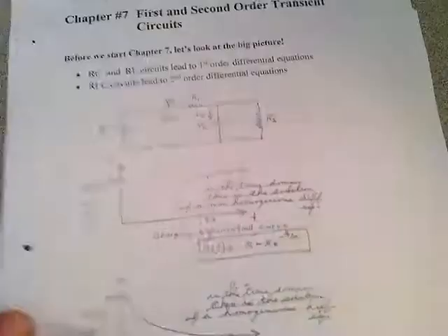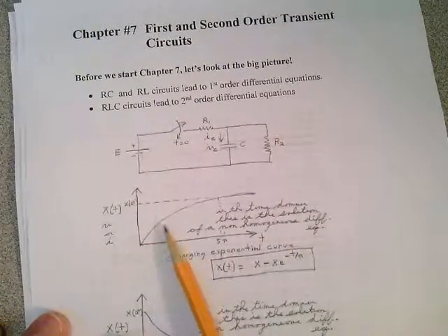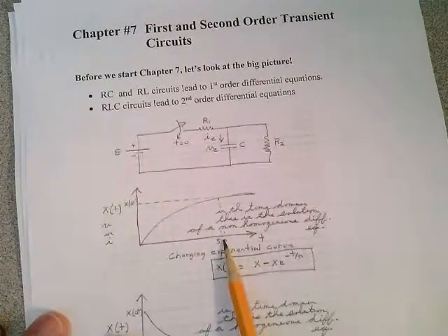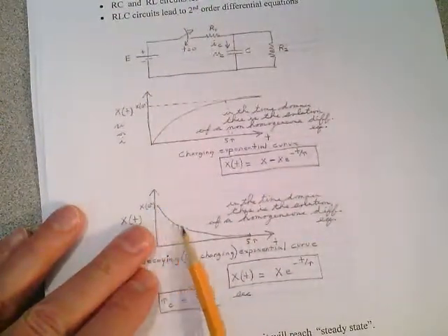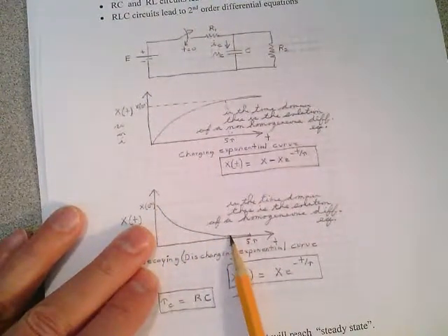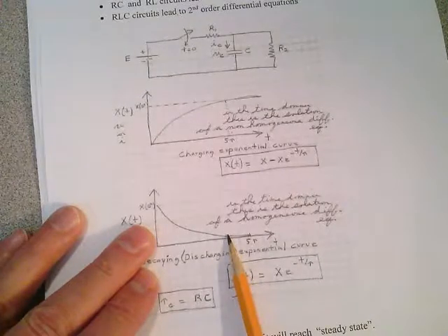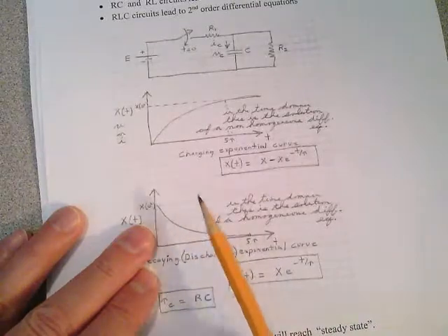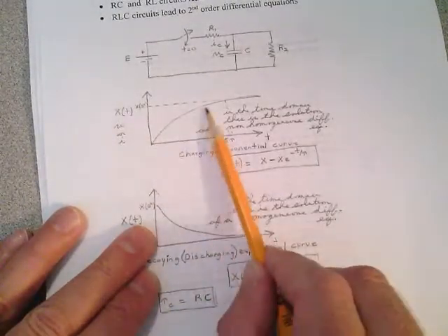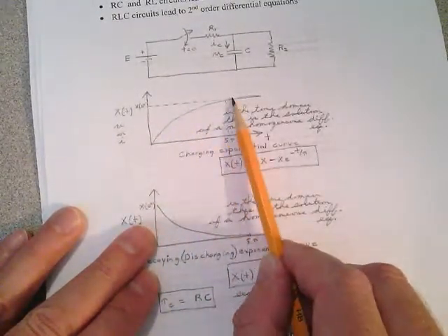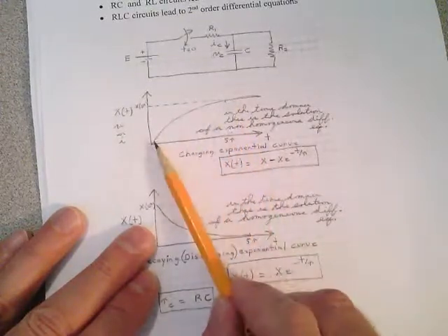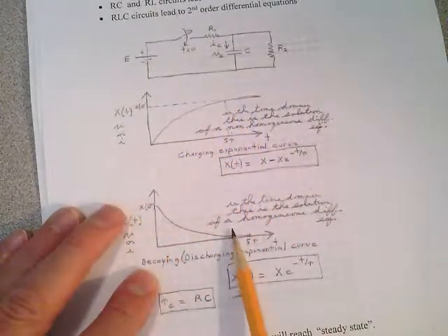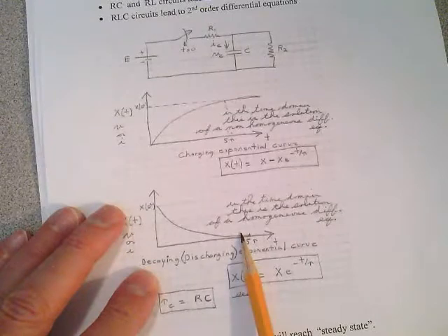It's reaching a steady state 5 time constants to this point, or it's reaching its final decay state at 5 time constants to this point. So you have to look in terms of where you're going to be. 5 time constants where it's going to put you on the curve. You have to first decide, do you have a rising exponential, or a charging exponential, or a decaying or a discharging exponential.